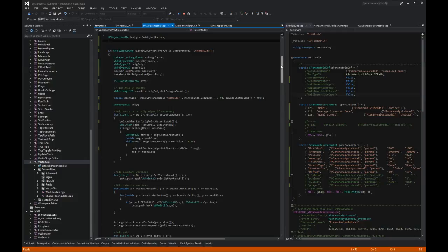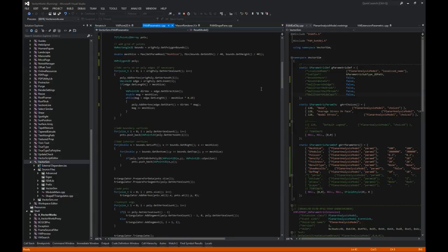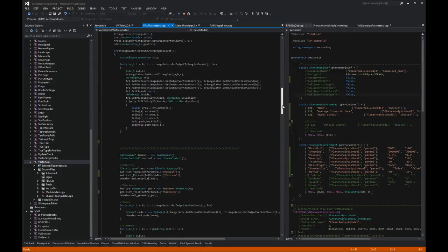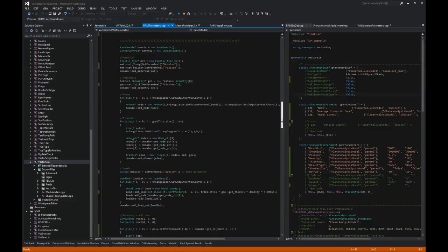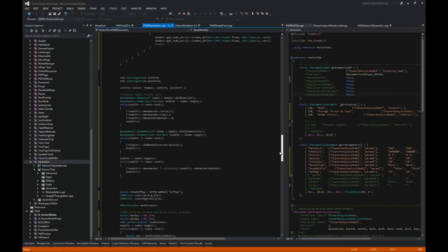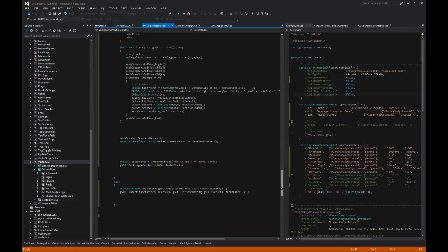It takes a 2D object, a polygon or polyline, out of the path group of a path object, and then it meshes the boundary, and then it creates an interior mesh, and then it builds up a list of finite elements, boundary conditions, and then runs the analysis and produces some results.